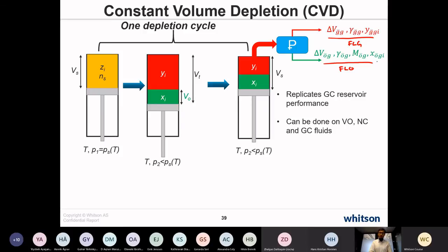So we measure the composition of the flashed oil, and you remember this nomenclature: O with a hat, meaning surface oil coming from the reservoir gas phase, the G, and surface gas phase coming from the reservoir gas phase. We analyze these compositions. We also have the volumes of each of these phases, and then we just do this mathematical recombination to come up with the composition that is in the PVT cell. And that's what the PVT labs report at each pressure stage in the CVD experiment.